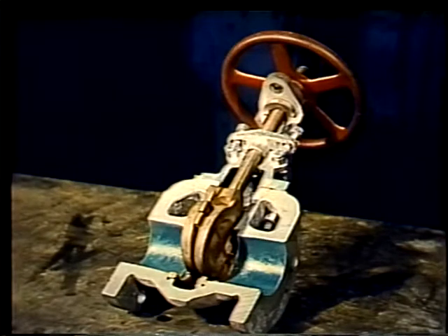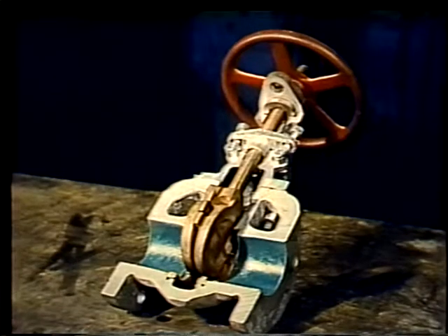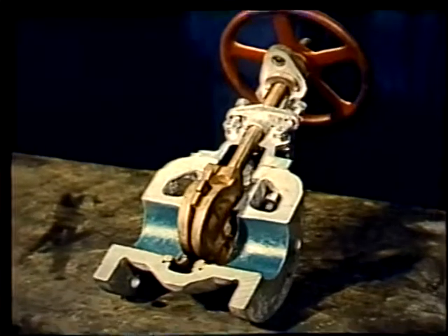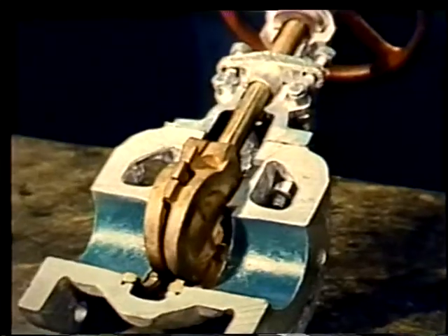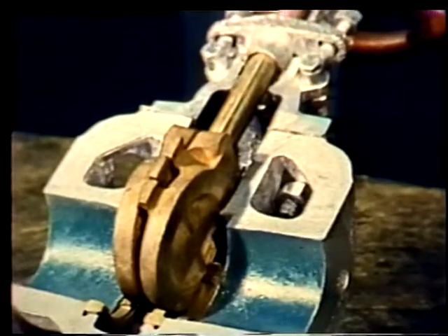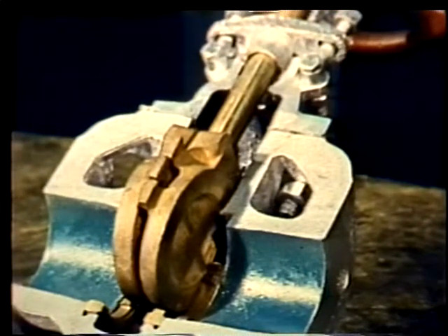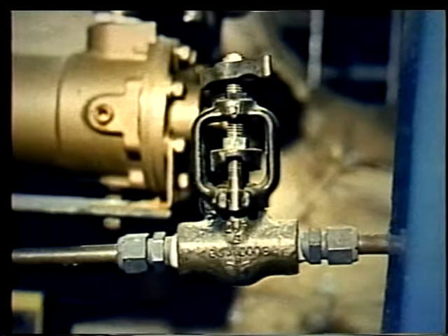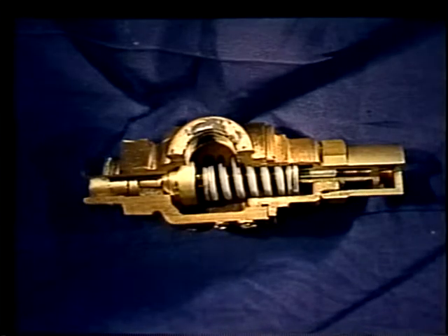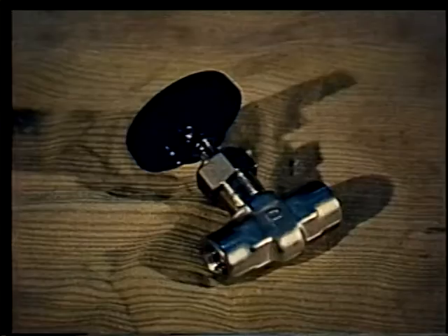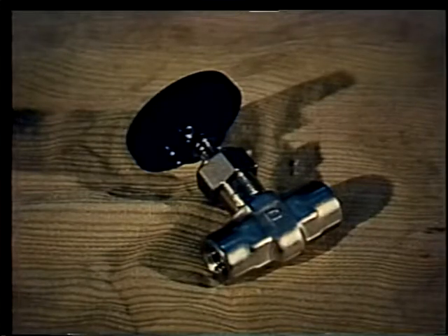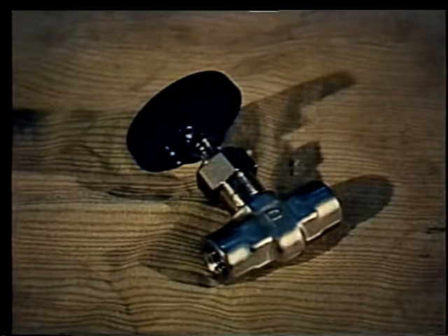Gate valves are made of various types of material depending on where they were used. For example, valves that are attached to low pressure, low temperature systems are normally made of bronze or brass. Cast iron valves are often found on low pressure steam systems or for lubricating systems. Valves used in high pressure, high temperature systems are made of special alloy metals. Stainless steel is used where there is a possibility of corrosion to the valve.